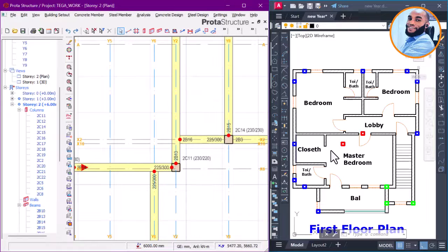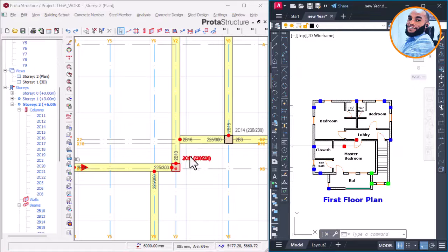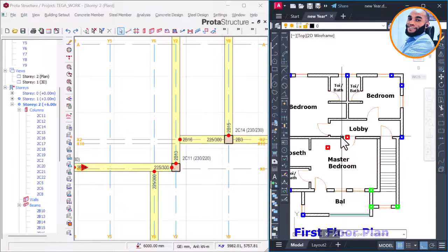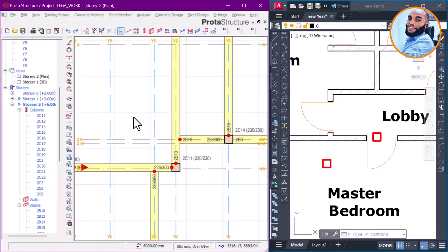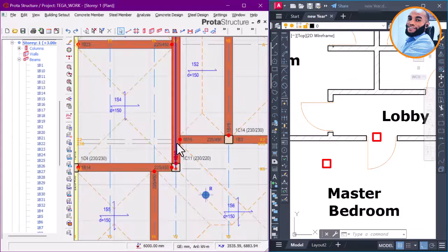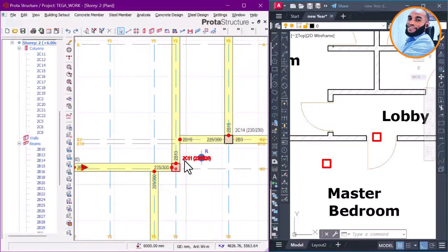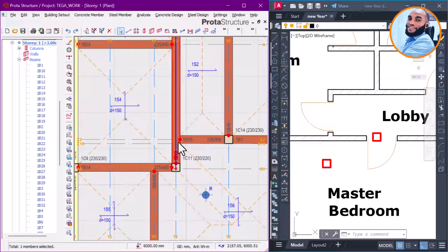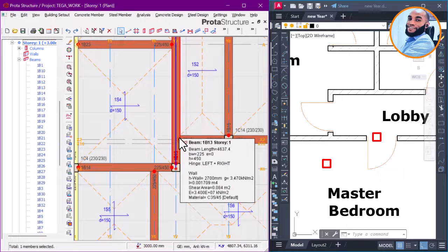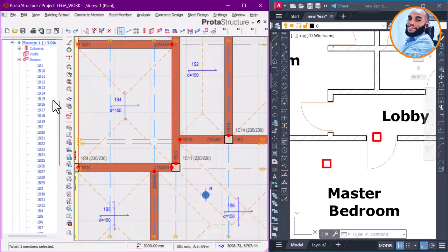Okay, that's fine. Looking at this, you can see that at this place here there's a small wall of 150. So invariably, I can make a beam sit directly here, just watch. If I shift this column here to this point, that column will still be hiding inside the wall, but it will be sitting on a beam on the first floor, as you can see on the floor below. All right.